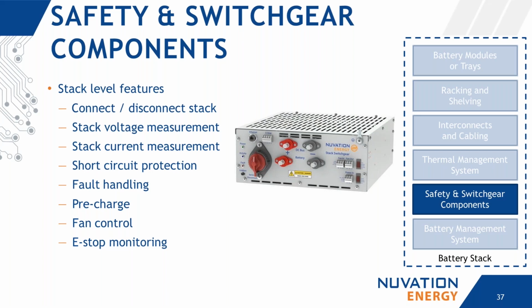Now we are into the safety and control components of the battery stack. Here we've got a list of some important stack level features. That includes connecting and disconnecting the stack, stack voltage and current measurements, short circuit protection, fault handling, pre-charge circuit, fan control, as well as e-stop monitoring.